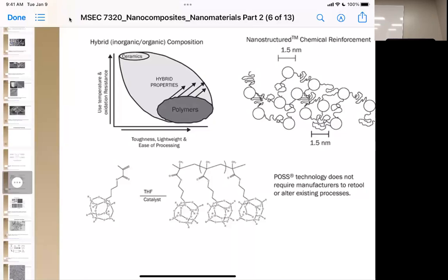And the way that happens is because you can polymerize not only one side, but multiple sides, you can get these free volume areas in your polymer matrix. The polymer matrix tends to be less structured and have a lot more flexibility at room temperature. And so the gases permeate there, having that free volume to hold those structures.